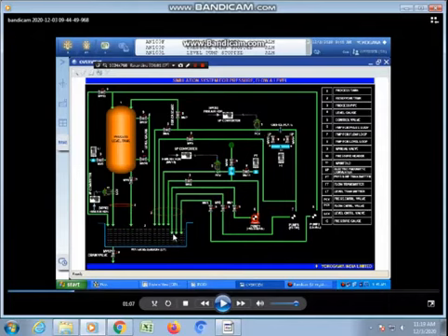The third loop we have is the pressure loop, which takes the water from this tank. We are using a pump. Then we have a pressure header, where the pressure is made. That pressure is measured through a pressure transmitter, which is a differential pressure transmitter, and this pressure can be controlled through the control valve. The outlet of this pressure is controlled through this control valve. We have the I2P converter, which is controlling the pneumatic air going to this particular control valve.